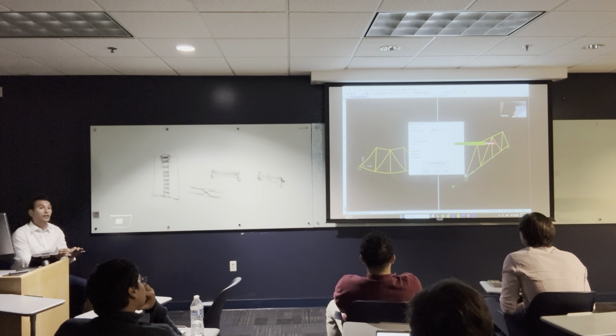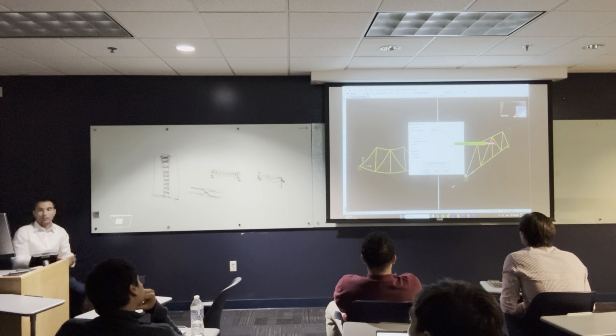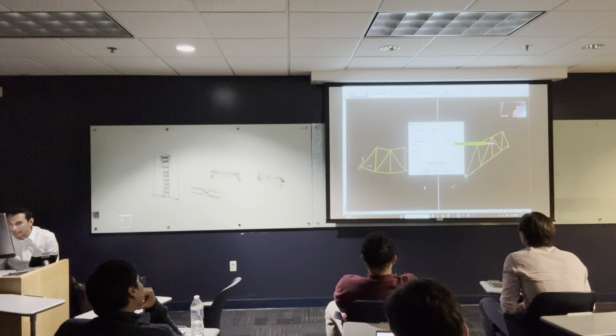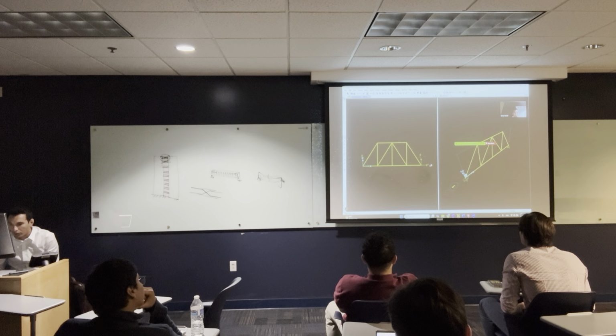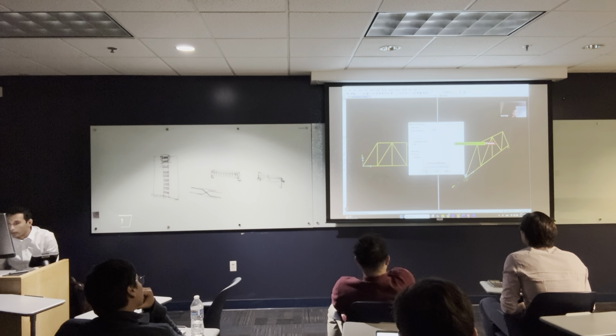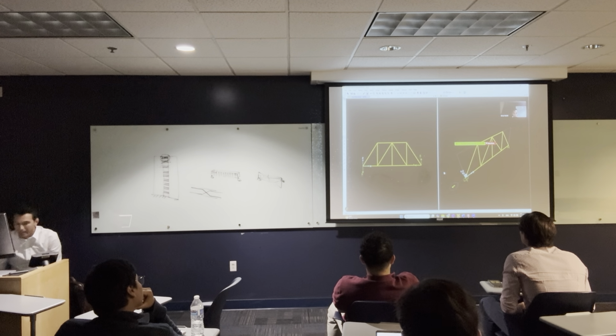It's going to ask me, do you want the reactions from the dead or the live? I'm going to ask, I want them from the dead, and I'm going to say OK. So it's going to show you, here's 2 reactions, here's 1 reaction. If you want to show reactions from the live load, I'm going to hit live load, hit OK. And actually that makes sense.